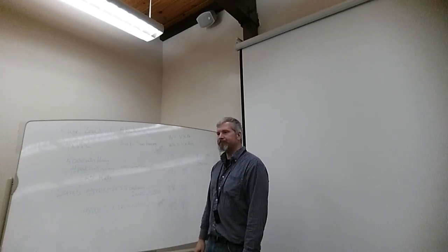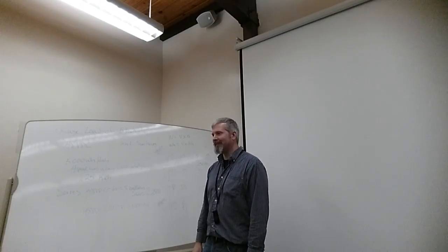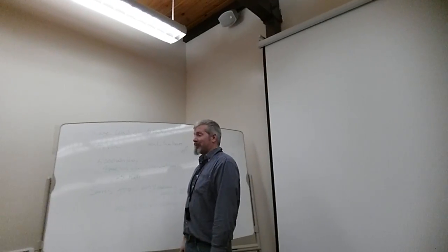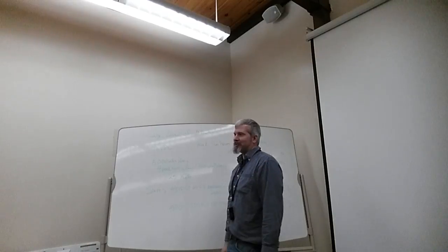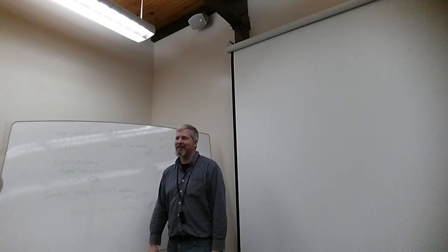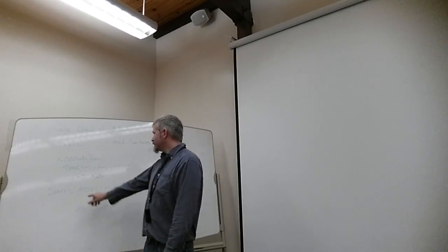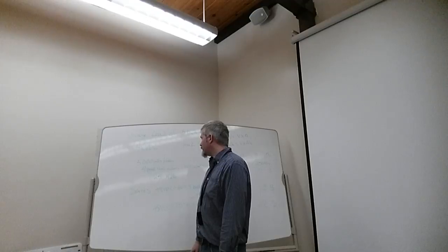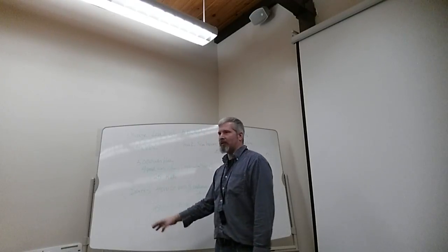We know everything's good. But what if it keeps raining for 7 days like it's doing right now? Well, this is on average. We get 6 during the summer and we get 2 during the winter. So we're out of luck for the next 3 days if we don't see sunshine. Well, we're still getting half of the power. So we're still producing 675 watts every day that would be filling this battery back up.